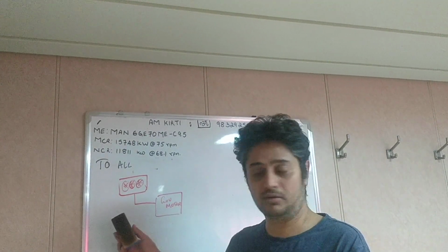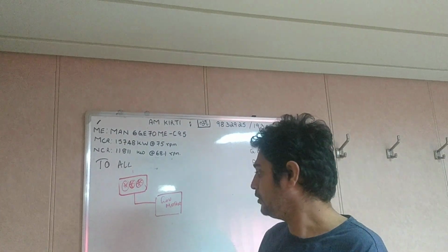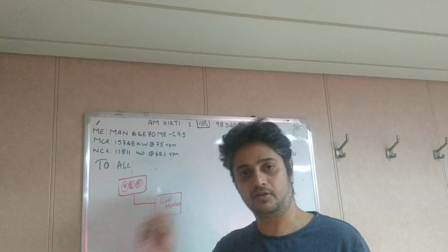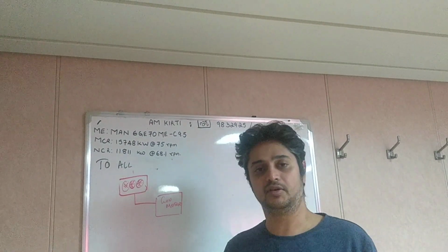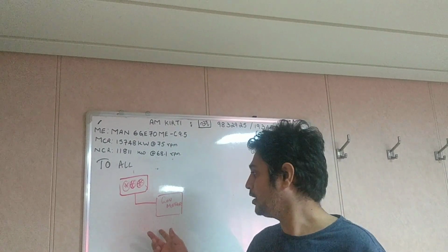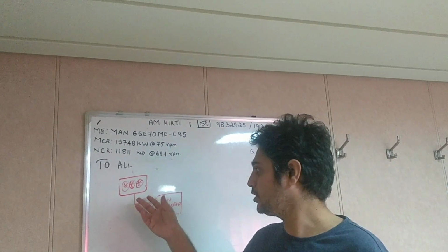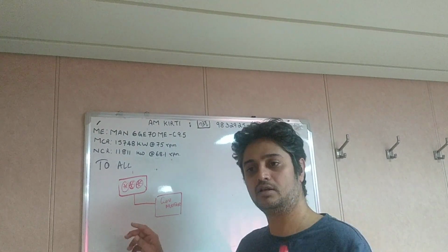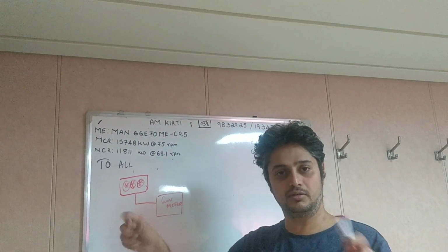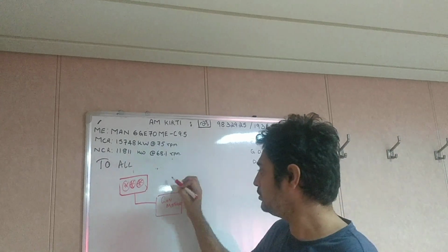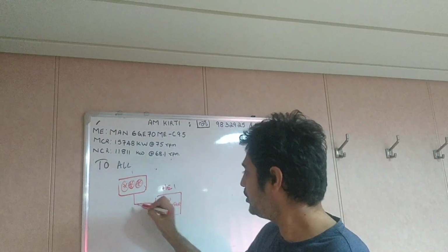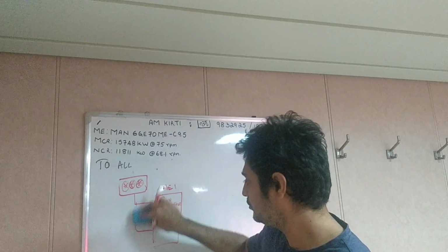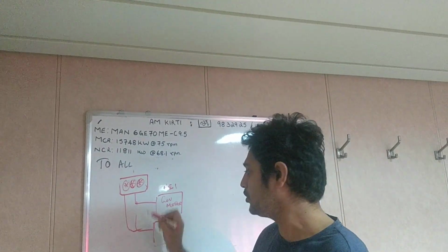So what I am trying to tell is, from the MSB, when two generators are running, you would have noticed a tuck tuck sound coming from the MSB, the synchronization panel, where these switches, because the PMS system is in auto, will give one generator an increase and another generator a decrease. These signals will go, for example, for AE1 and for AE2. Just for example, I am taking.